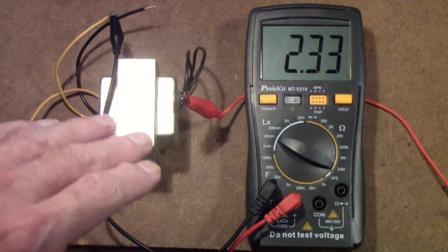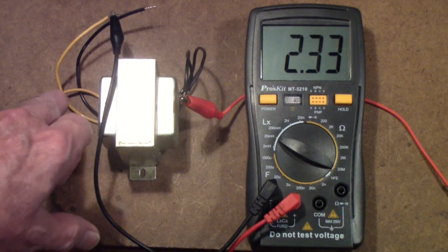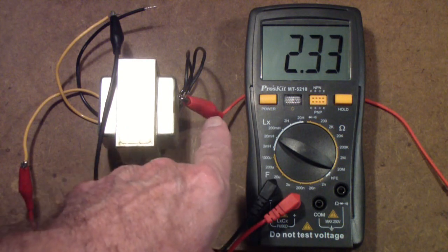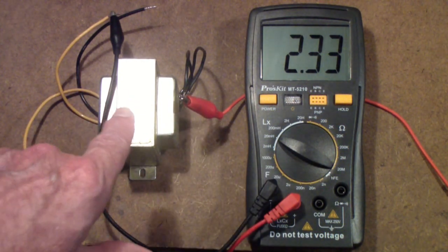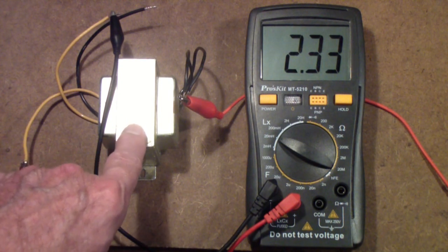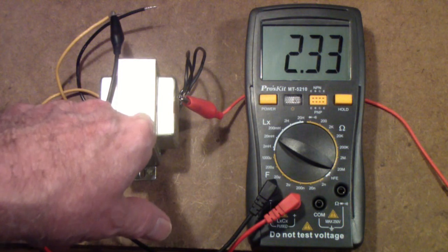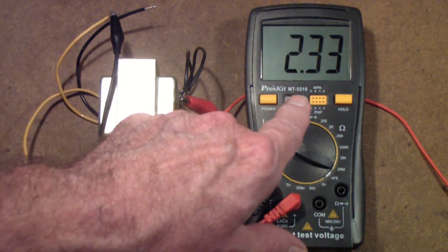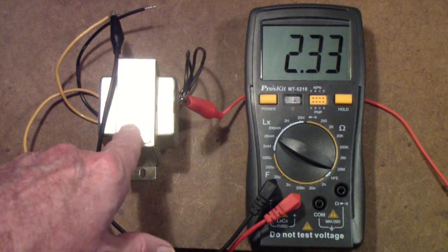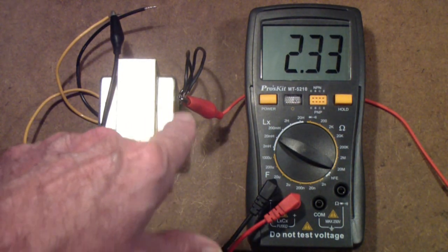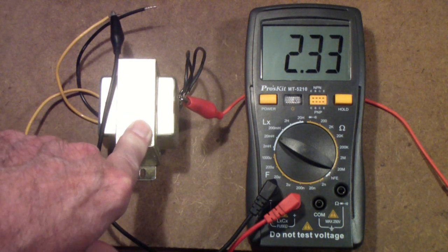But if you remember, you take the ratio of the inductance with the output open to the inductance with the output shorted to calculate the relative efficiency of this transformer. Because the leakage inductance is a little higher now, instead of about a 15 to 1, we're getting about 14 to 1 in terms of the power transfer.